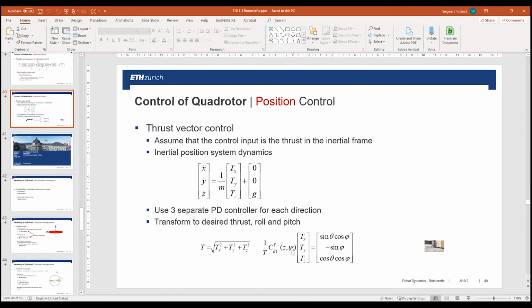Of course, this was not detailed in the lecture. You always have to have knowledge about the angles and the position of the whole system. And for the angular control, typically you have the IMU. The IMU is giving you accelerations in X, Y, Z and rotational speed around the 3 axes. So this is directly used as the input.